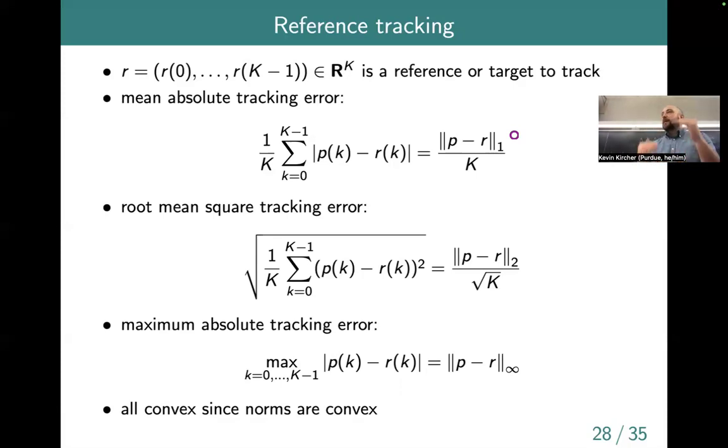And we talked about how the basic problem of power grid operations is to balance supply and demand. When supply of electricity dips below demand, then the frequency on the grid will tend to sag. So it might go from its nominal 60 hertz to 59.9 or 59.99, something like that.